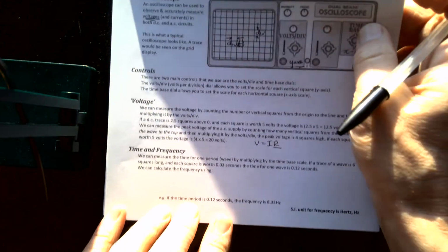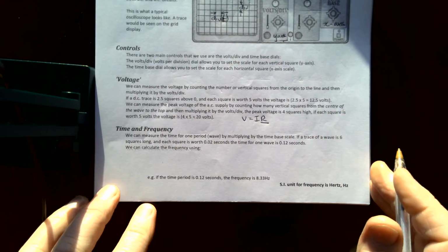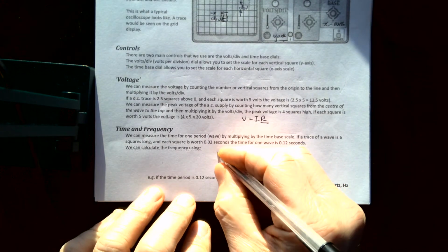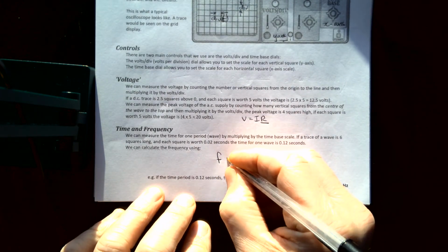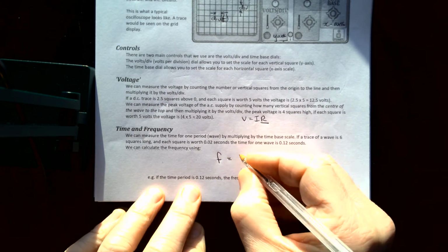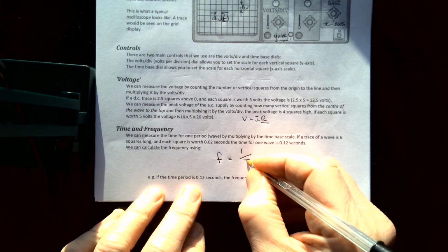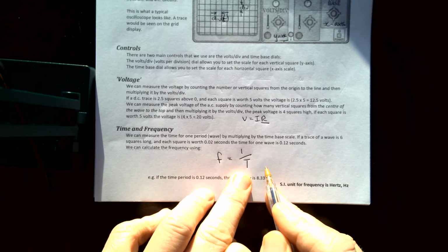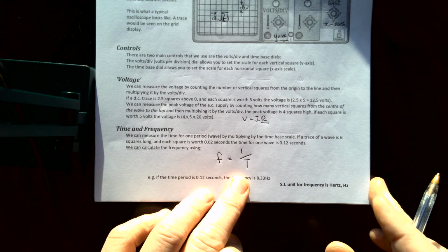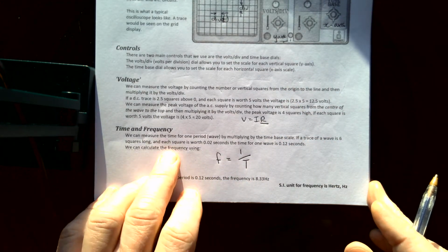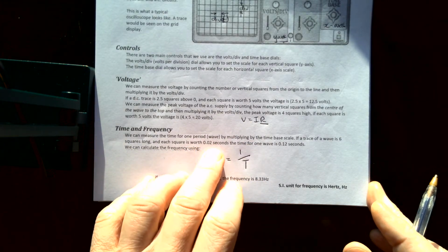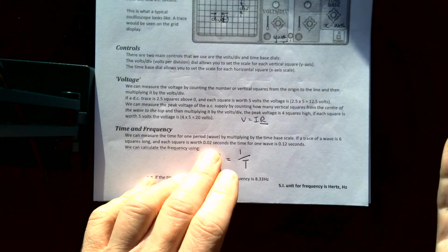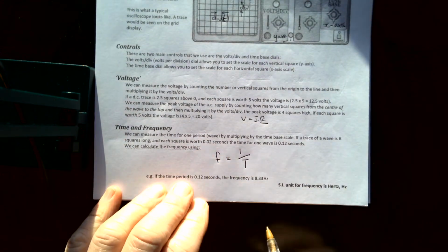Frequency, give an example here. So again, you can work it out, etc. But how do we use it? Well, it's just the standard equation. You're going to measure time. So the frequency is waves per second. You just need the time constant to give you seconds per wave, or milliseconds per wave. Okay, so fairly standard kind of tracing. That scale is commonly used because most things tend to be mains, and we're looking at 50 Hertz. So that's 2/100ths of a second.